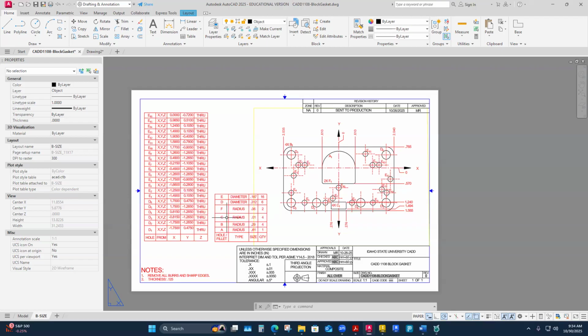This is why you have your drawings checked by a second eye, because they may catch something like that. I'm decreasing the accuracy of that radius by carrying the wrong decimal places, so that's super important not to do. Anyway, what I was going to go back and say is that there's just data that I can't get into the table. Yes, I can get their coordinate points, radii and diameters detailed in a table, but some of these features of size, like this odd shape here and the rectangular shape, aren't captured in the table.